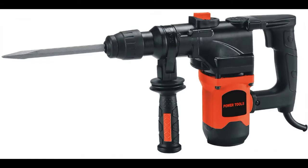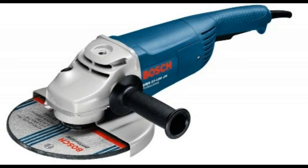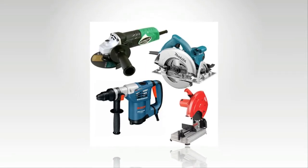Joiners. Joiners are specialized woodworking tools that use a saw blade to cut a thin slot into a piece of wood. A similar slot is cut into another piece, and the two are joined by placing a single piece of glue-covered wood into the slot and pushing the pieces together. Jointer. This tool uses specialized blades to cut the surface off a piece of wood, making it flat.